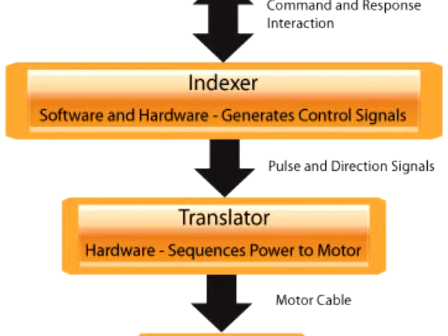For each signal that it receives, the translator only has the capability to rotate the motor's shaft from its current position to its next adjacent position. However, input signals provided to the translator in timed succession are used to accomplish more complex motion. The functional unit that provides these signals to the translator is called the indexer.